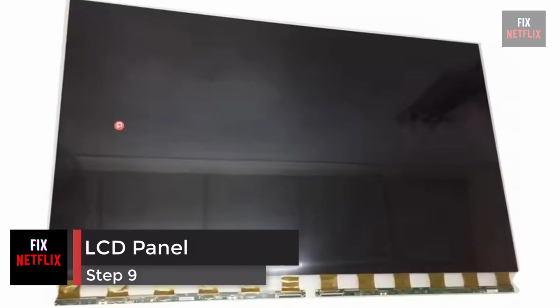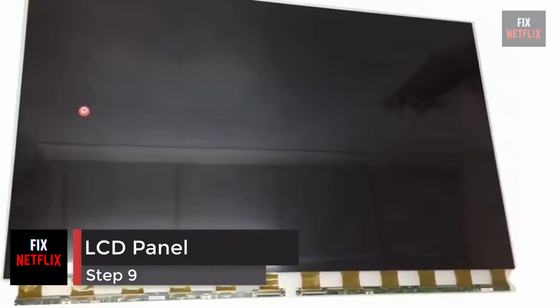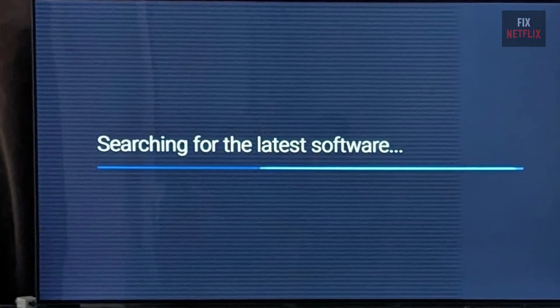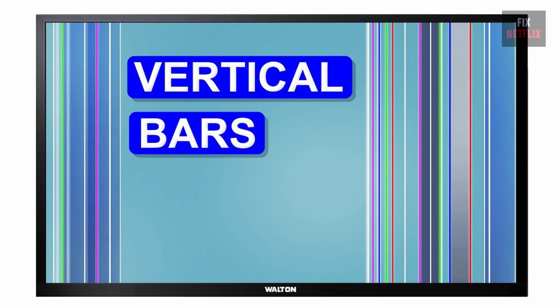Step 9. LCD panel. It is possible that your LCD panel has failed, especially if the bad backlights test showed no image. A common sign of panel failure is single horizontal or vertical lines in the image on the screen.